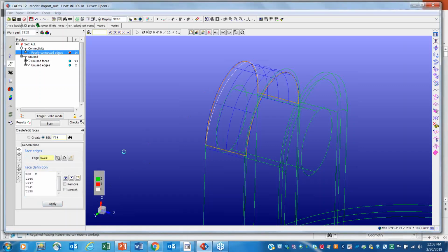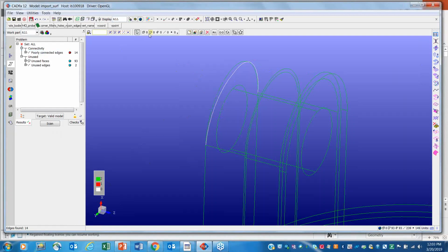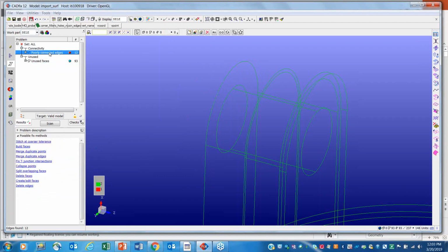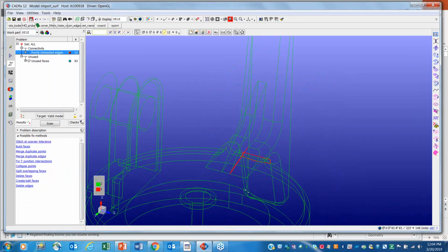I use the same surface that's already there. It's actually already extended to the right place anyway. And so what I've done is redefine that face as appropriate. You can see we have a white edge remaining. That's an unused edge, or in this case, two unused edges. And we can always just clean them up and delete them as needed. So a couple more areas here.